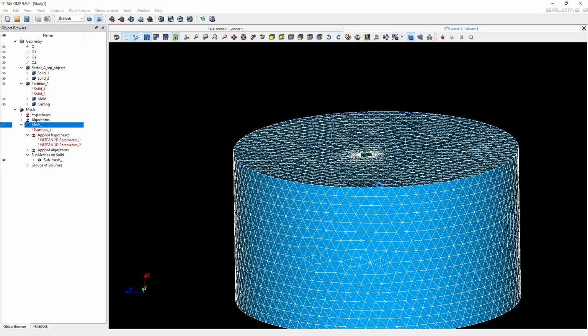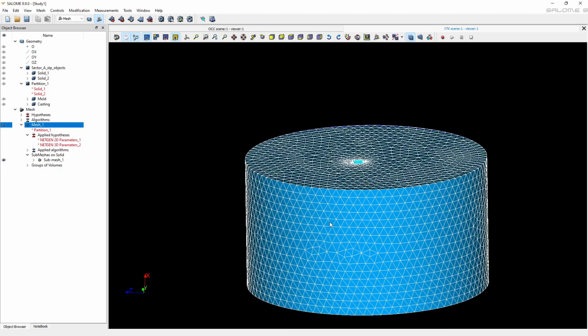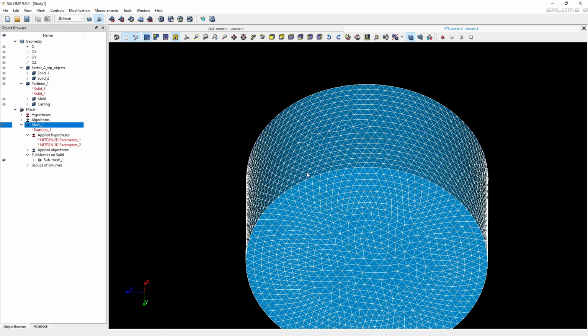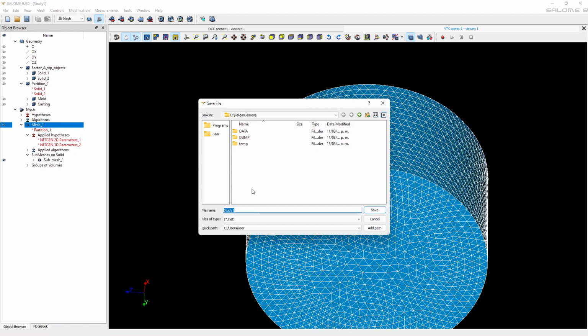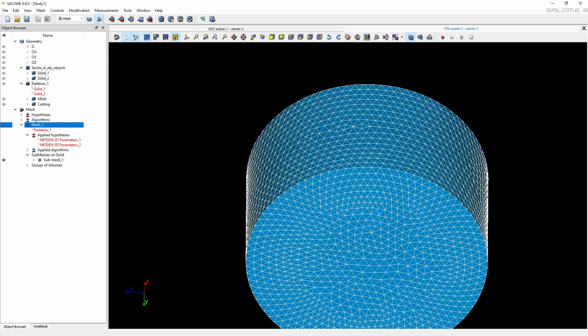Everything is ready, but I also recommend saving the entire project in the Mesh Generator's HTF format, as the history of operations we have done will be stored there. In case we need to make changes to our mesh in the future, we will not have to perform all the settings again. That's all. We have finished working here. We close. In the next lesson, we will see how to set the main parameters to perform calculations and also prepare and start the casting calculation.